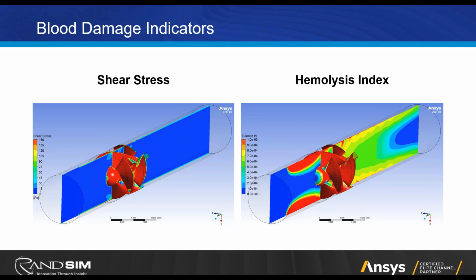The magnitude of the hemolysis index is not really what's important. It's relative to your future design. You say, let's try to improve that, and then we compare the hemolysis predictions between design A and design B. What I did here is try to balance it with the shear stress plot so we could make a comparison between the two. I'm trying to highlight what you would miss by just looking at shear stress as opposed to shear stress and hemolysis in these simulations. Hemolysis models are relatively new. They've been around a while, but mostly in academia. These days, they are used more widely in the industry.